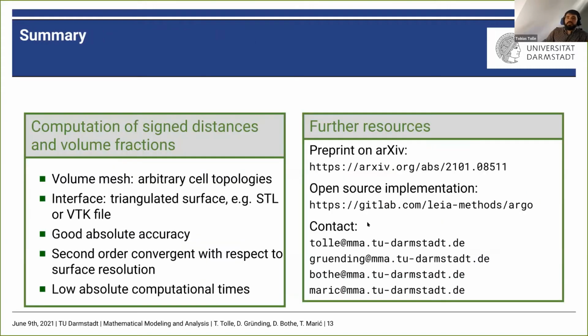So to summarize, we have developed a method that can initialize signed distances and also volume fractions on any mesh type that is supported by OpenFOAM. As an input, one needs an oriented triangulated surface. This can be an STL file or a VTK file.